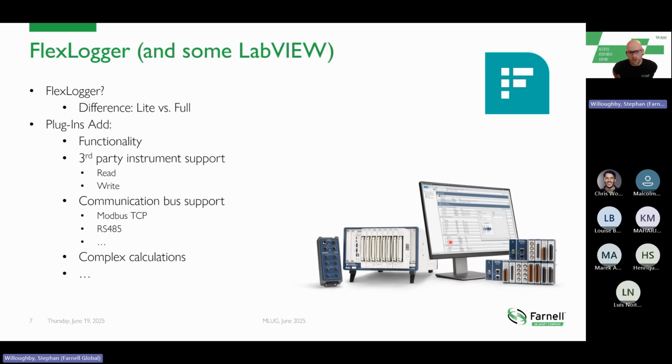So kind of like how you can do Instrument Studio configs and then include them in things like TestStand, you can do that with FlexLogger within LabVIEW as well. So yeah, I guess you could use that. At that point, I'd probably suggest it won't be as lightweight an application as it could be if you did your own DAQ. But yeah, to get off the ground quickly, then yeah, possibly.